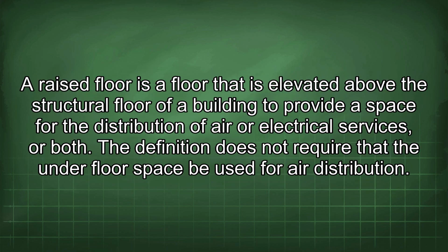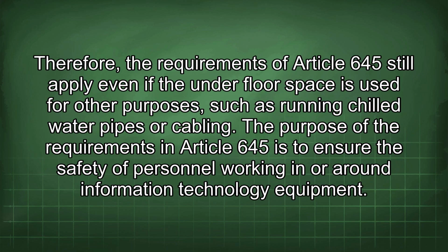A raised floor is a floor that is elevated above the structural floor of a building to provide a space for the distribution of air or electrical services, or both. The definition does not require that the underfloor space be used for air distribution. Therefore, the requirements of Article 645 still apply even if the underfloor space is used for other purposes, such as running chilled water pipes or cabling.